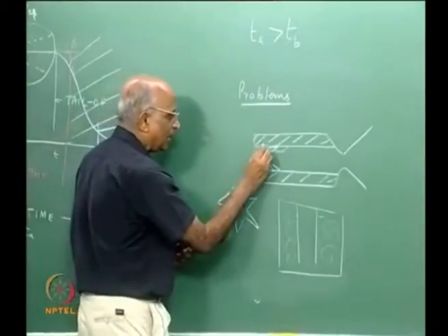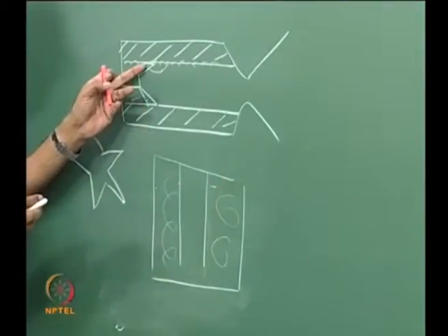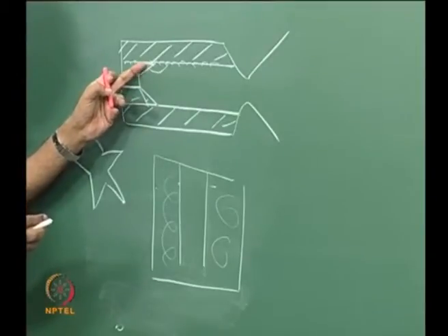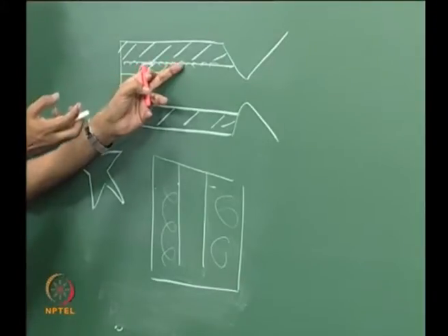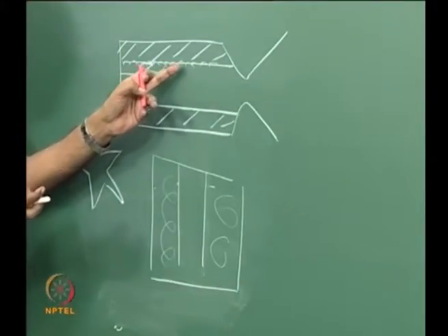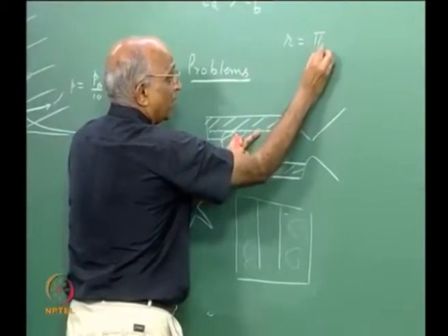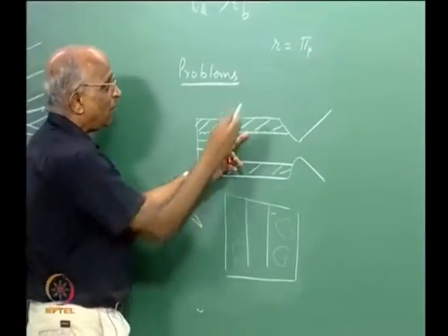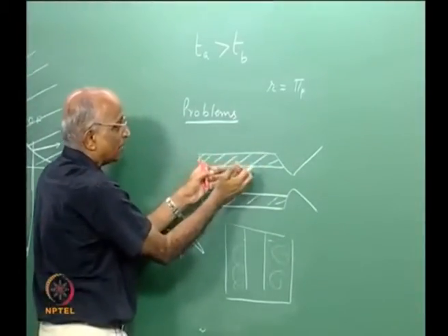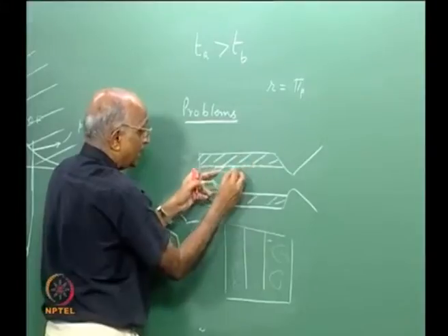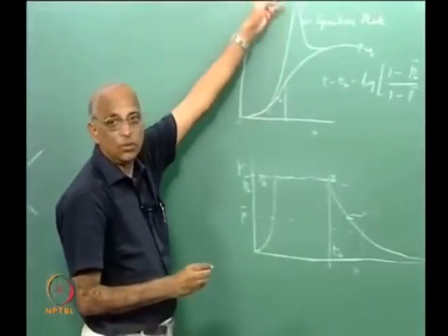Now if the surface of the grain is such that it is not easily ignitable, what happens? You are transferring energy, the grain gets heated, and as it continues to get heated, when it begins to burn, it starts burning at a higher temperature. Since it starts burning at a higher temperature, the value of R is now influenced by the temperature sensitivity factor, and therefore it produces much more mass, or it burns with a higher speed, and therefore you have a higher amount of mass energy getting released, and therefore the pressure could go up.